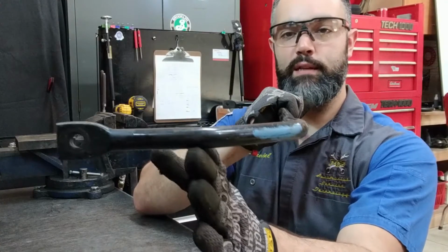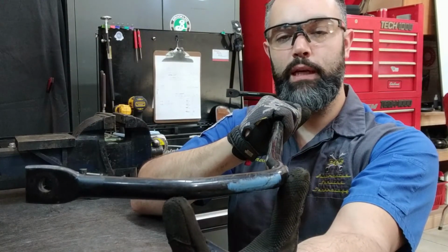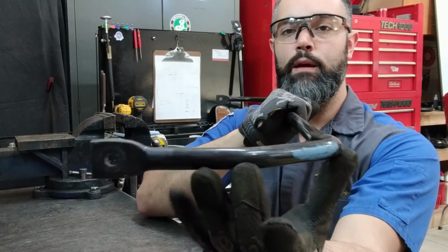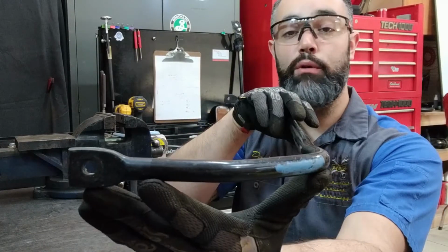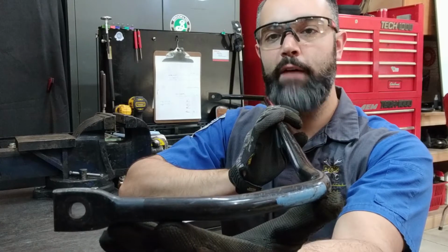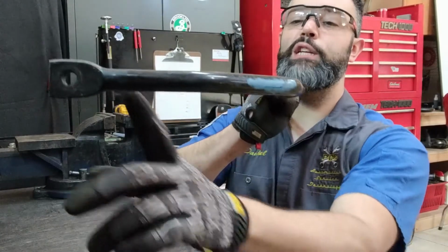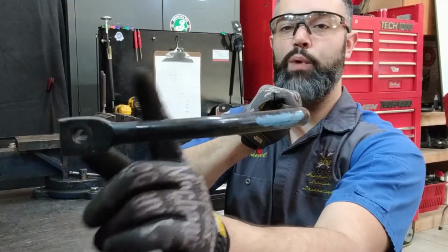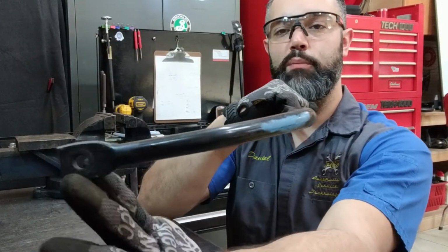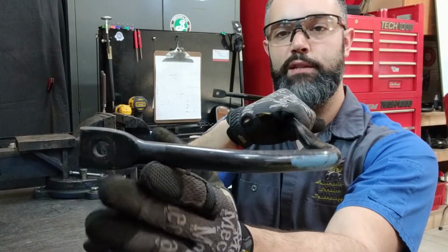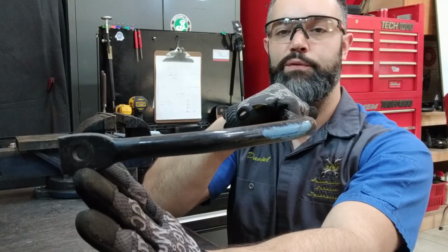A shorter distance is going to result in less leverage on the sway bar and will increase the stiffness of the sway bar. A longer attachment point from the pivoting part of the sway bar will result in a less stiff sway bar. Aftermarket sway bars and sway bar kits offer the adjustability of changing through multiple positions where that link is going to connect. So a person can tune their suspension to their preference, let's say in a race application, move it closer in to stiffen the sway bar, or move it farther out to soften the sway bar.